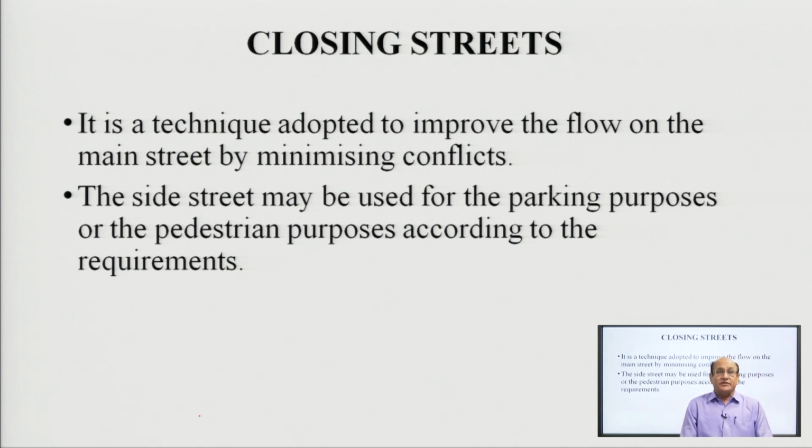Closing a street. It is a technique adopted to improve the flow on the main street by minimizing conflict. The side street may be used for parking purposes or pedestrian purposes according to the requirement.